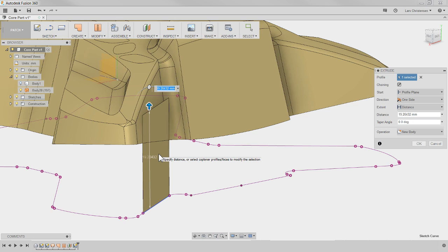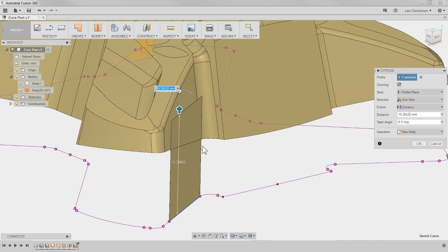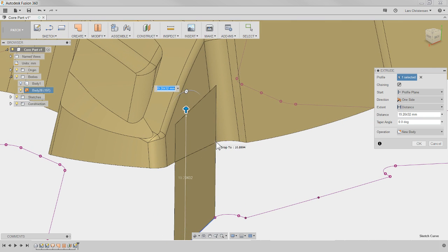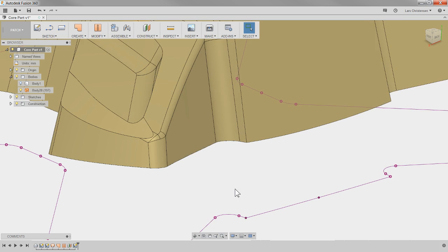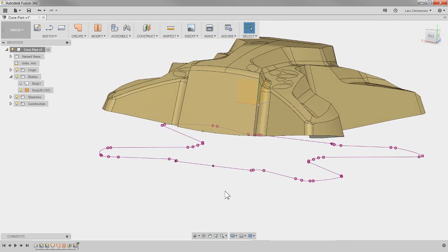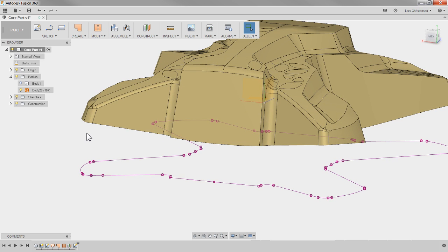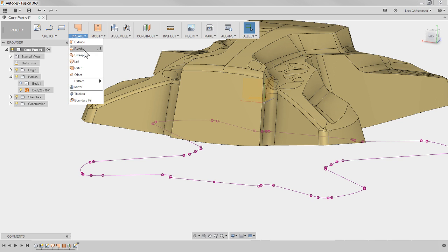But be aware of that trimming, and I'm going to show you trimming in a second. The software really has to solve, everything has to be accurate. And since we're projecting down, this software works down to 12 decimals. And if there's one of them that is off, you can actually be struggling. So instead of trimming geometry to one another, it's sometimes better to actually develop the geometry. To do that, I'm going to go in and use the loft command again.